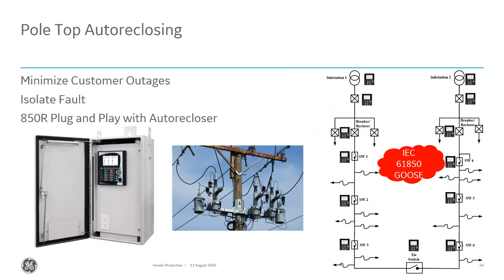So what happens with reclosing is that the recloser senses the fault, trips, waits for a certain period of time, then closes the breaker or recloser back in, not into the fault, but into the power system. And if that fault is still there, then it should retrip. And if the fault is cleared, then it goes about its normal operation and the load is restored.